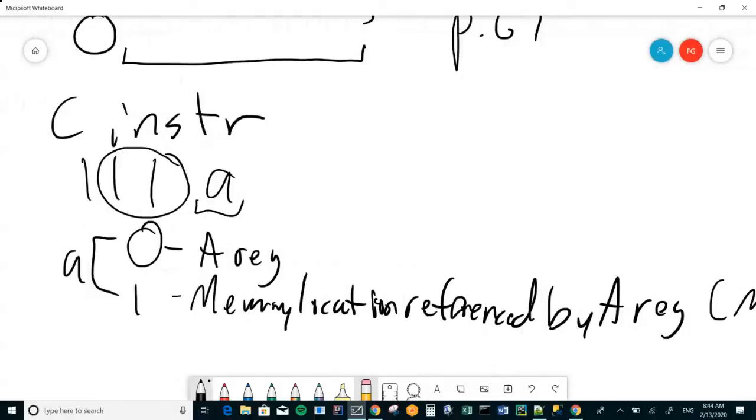This gets back to the theme that in a CPU, you're constantly trying to do everything. Everything that you're trying to do is the universe of everything that's possible to do. If you want a possibility, you have to wire it to actually be making it happen at all times. The select bits and the load bits then are the gatekeepers saying, this time, this is what we want.